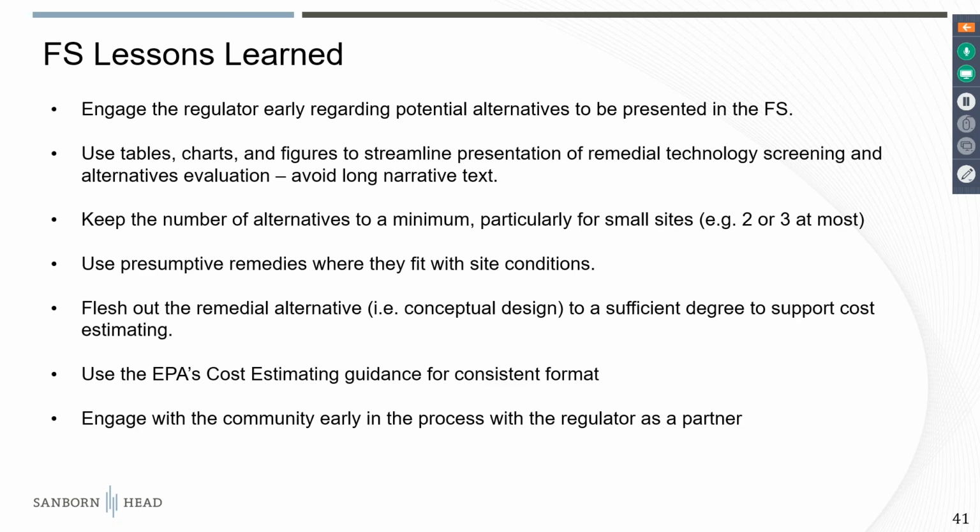If you can use a presumptive remedy, that would be great. Just be cautious. That doesn't mean you can stop thinking about how it's going to work. You still need to bring in all the important information to assess that remedy, site geology, the site characterization, etc. To get a good cost estimate, you need to flesh out the remedial alternative in sufficient detail to support your cost estimate.